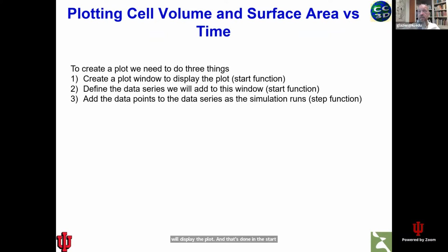We have to define the data series we're going to put into that window. We can have one or more. And the formatting of the plot. That's also done in the start function. And then we have to actually add the data to that data series as the simulation runs. That's done in the step function.